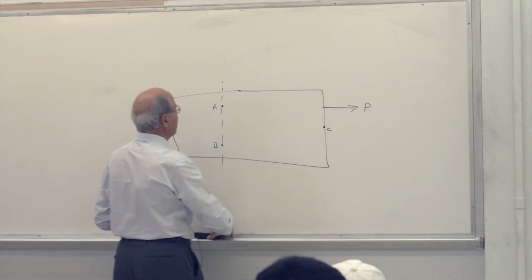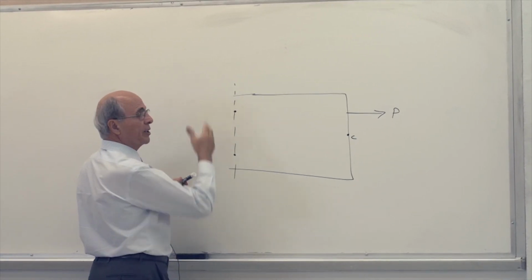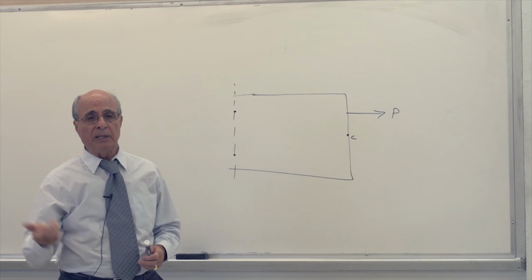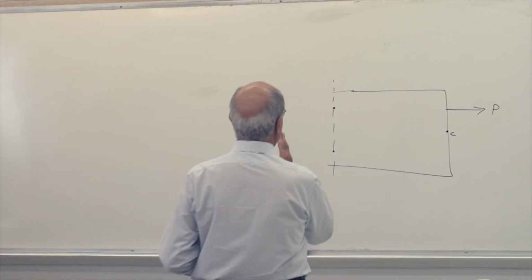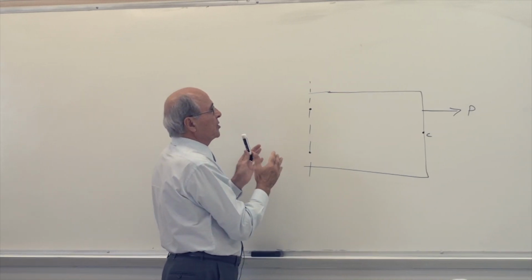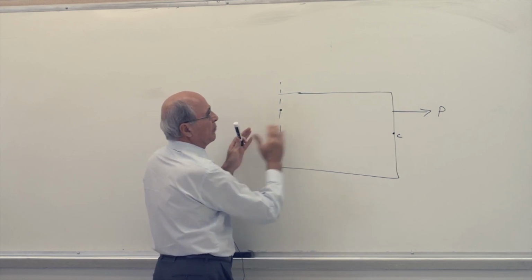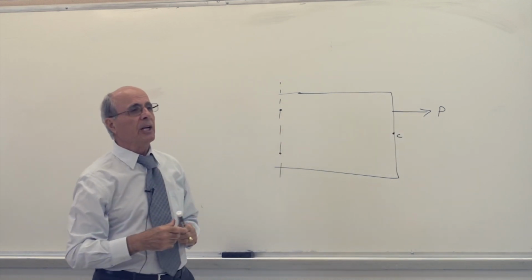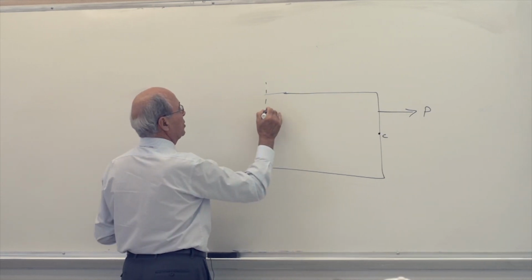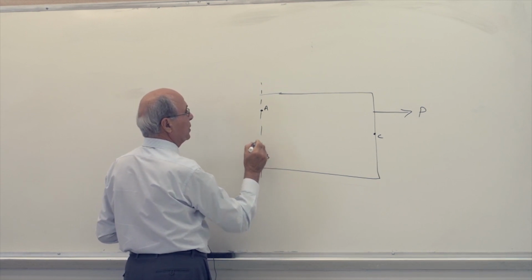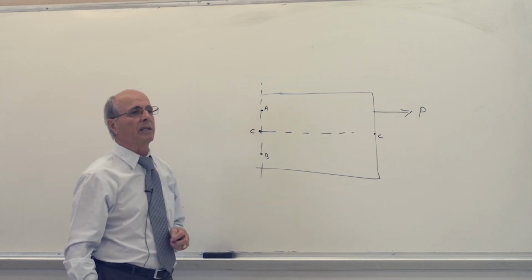You keep the load there. Then you go to this cross-section and make a cut there. And as we did in many homeworks, including homework number 1, you come to this section. What stresses is about what's happening in this section. And that section with this force must be in equilibrium now. Everybody understand that? So here I'm going to do the equilibrium. This is point A, this is point B. Obviously, this is the neutral surface, so this will be the neutral axis there, correct or not?